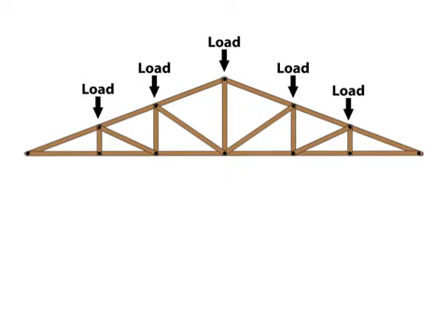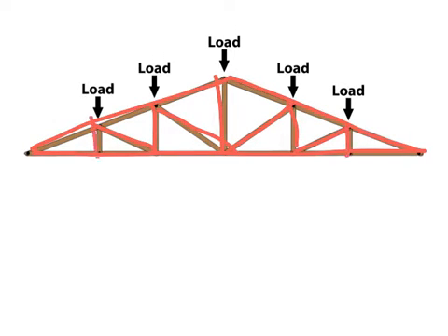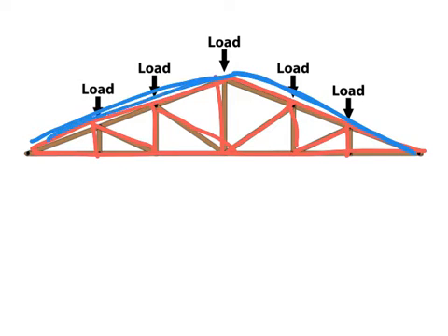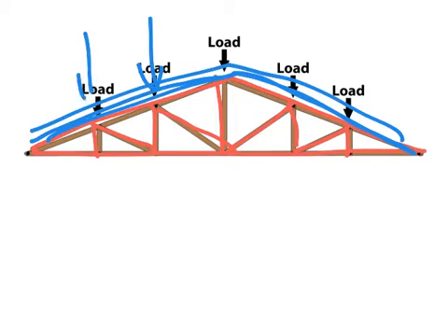This is a typical wooden truss that's found in many homes in America and New Zealand. It's a wooden frame made up of different components or parts, and when you nail or bolt them together, you get a whole series of triangles. Then typically on top is all the wood framing and the roof materials. So you can put a very heavy load on a truss. It could be covered in snow, and the truss will support the roof.